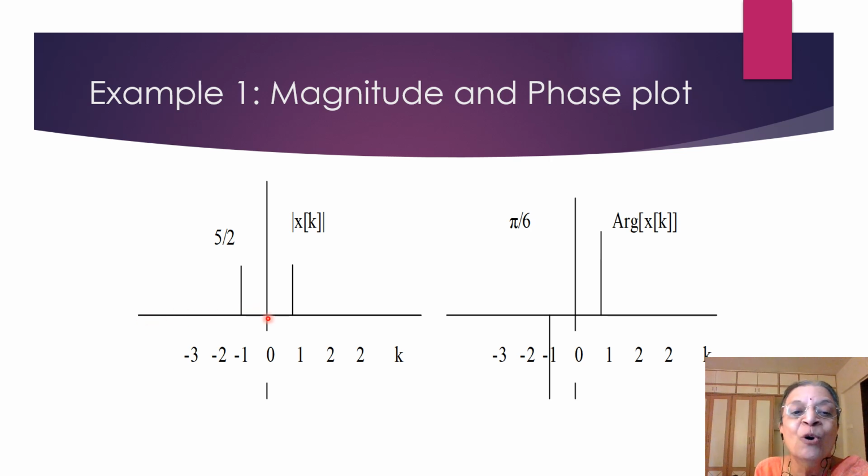Otherwise, there is no meaning attached to these negative frequencies. Remember, we are supposed to consider only the spectrum on the positive side. We just replicate it on the negative side because we are using exponential representation. Otherwise, this particular negative side need not be plotted at all.